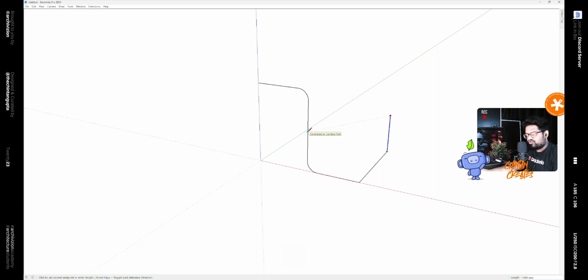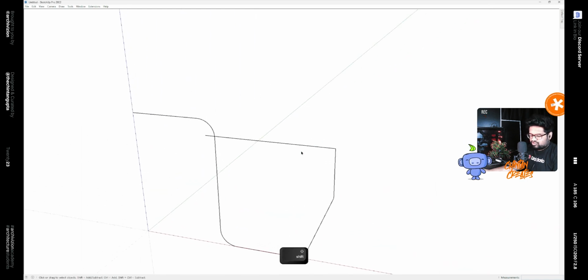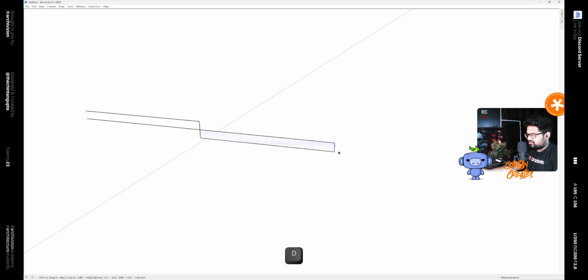or the midpoint of your staircase of this line. And then in the red direction till here like this. Now from the midpoint of this line, make a line for 150 millimeters. So this will be like the riser of your staircase, and then finish it off like this. And then again 150 millimeters, and then over here like this. After that, you can delete these lines and the surface and these edge.